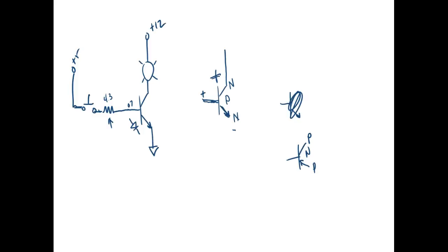Now, what we get out of a transistor is that the base current is almost nothing, and the emitter collector current is real big, so we get what we call a current gain. And we call this the beta. So a transistor has a rating of a beta. The transistor we're going to play around with is a 2N3904, and this has a typical beta of approximately 100. So that means if I press that little button, I'm putting 1 milliamp into the base. I would get 100 milliamps over on the collector emitter.